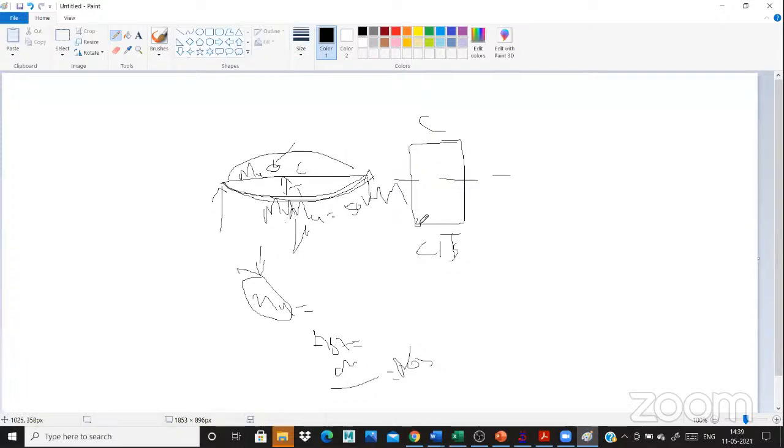For assumption, I provide 4 numbers of 16 dia bars. In the compression zone, I provide only 2 bars of hanger bars. Understand? This is the difference.